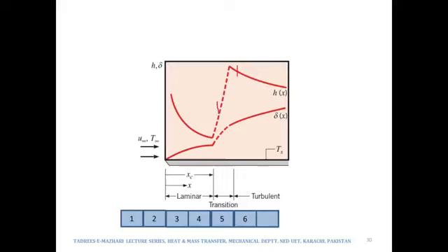These are the values of H that we are getting from the fifth heater. All those different values of H will result in different values of local Q, and therefore the average H would be H bar and the average Q would be average Q. So we will get an average Q, and that average Q would be due to average H bar, and that average H bar would be the average of all those values in this box.